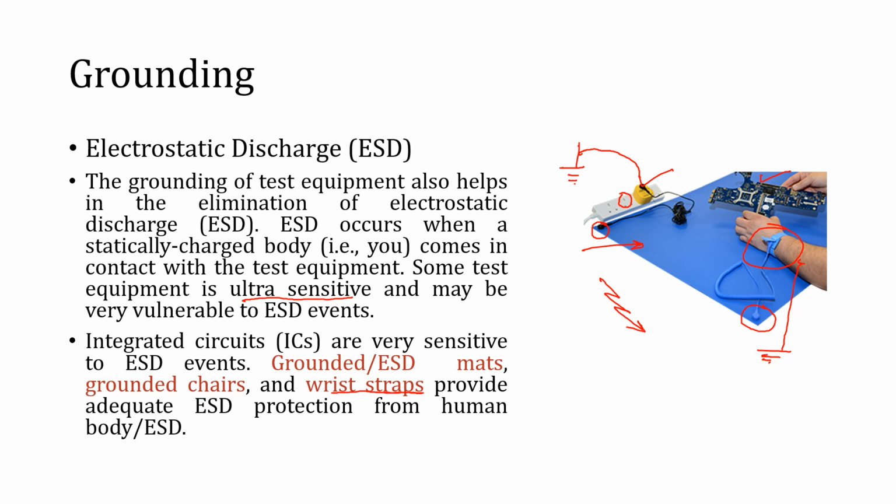So I hope that before today's lecture you were not so concerned with grounding and earthing, and now you can imagine how important it is. So be careful when handling very sensitive devices, whether they are memories, ICs or other devices, especially when there is a symbol like this. It means the device is very sensitive to electrostatic discharge.